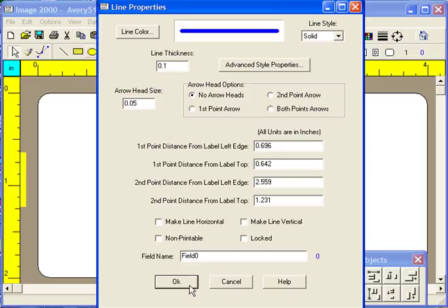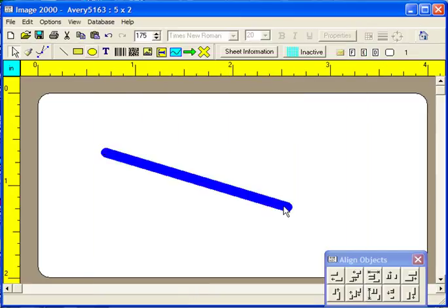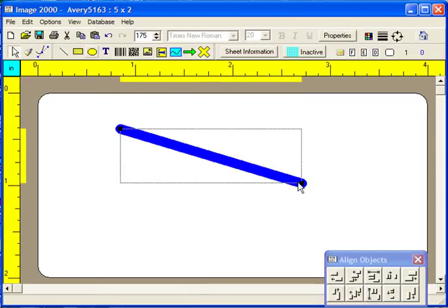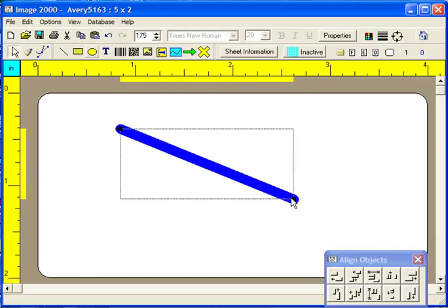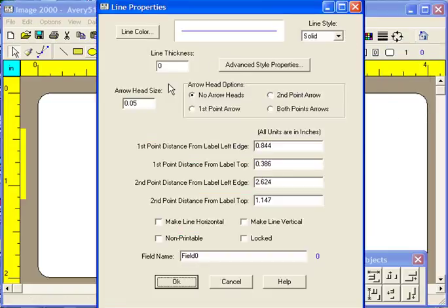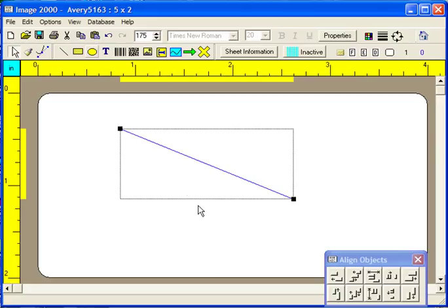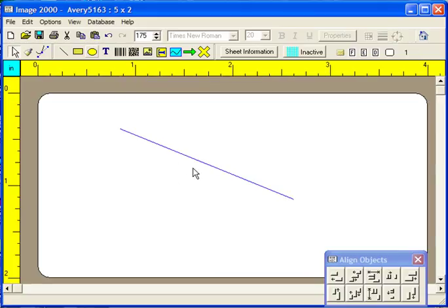If you make a line very thick without arrows, the line will appear to have rounded ends. The smallest you can make a line is 0.001 inches thick. You can also just choose the hairline selection from the line thickness tool in the toolbar. Entering a line thickness value of 0 is the same as choosing a hairline thickness that is 1 pixel thick on any display or printer.